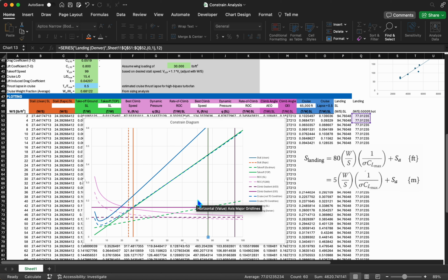Having a large wing adds weight to the aircraft. It also adds a lot of structural constraints because now you have this large wing. If you want to maintain a reasonable aspect ratio, it's a large cantilevered beam. So you're adding load further and further out. So it has compounding effects that forces you to increase the weight so you can withstand the structural requirements of having that larger wing and more distributed load.